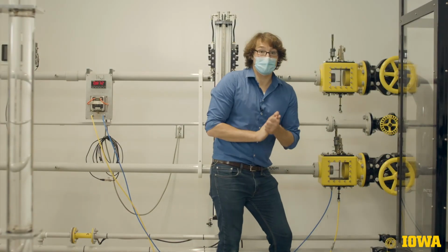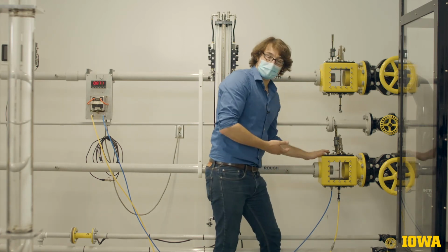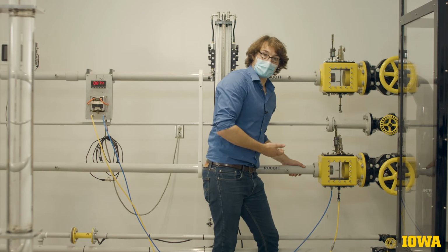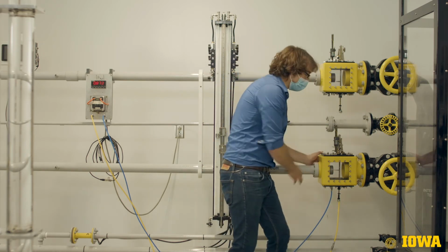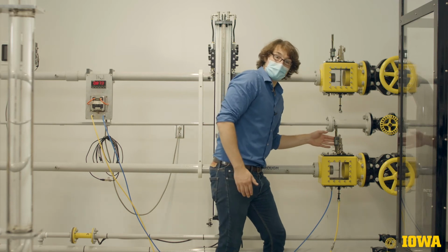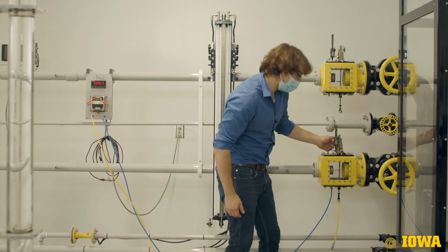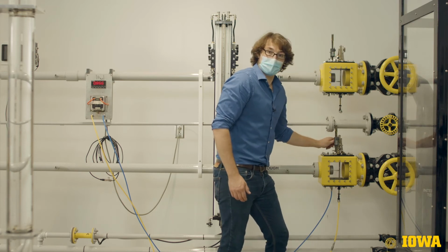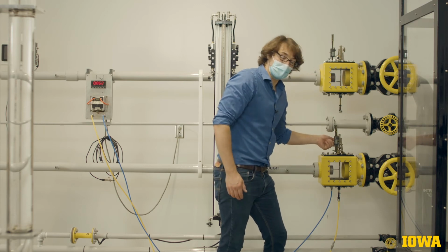So now that we have flow moving through the rough pipe, we need to duplicate our set of velocity measurements with the flow coming out of this other pipe. So we have another pitot-static probe, again with a set of calipers zeroed at the center line of the pipe, allowing us to measure the difference between the stagnation and static pressure at different radial positions.